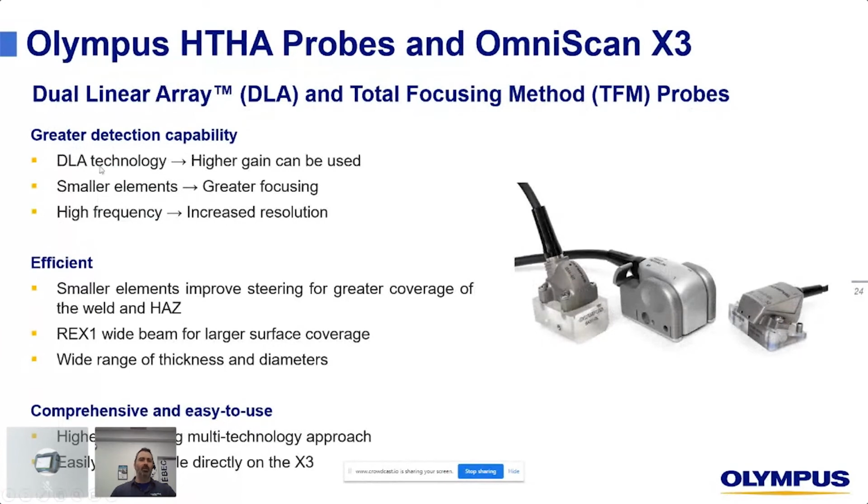Greater detection capability, DLA technology, higher gain can be used. Smaller elements equals greater focusing. Higher frequency equals greater resolution. Smaller elements improve steering for greater coverage of the weld. We'll see in the second study case